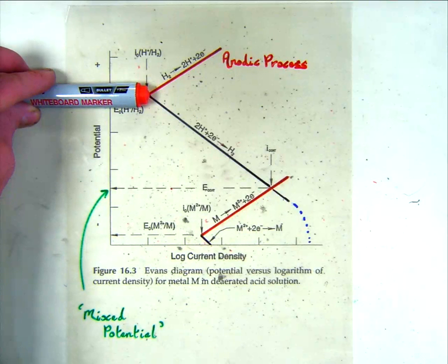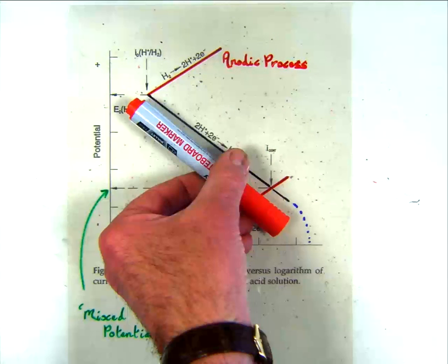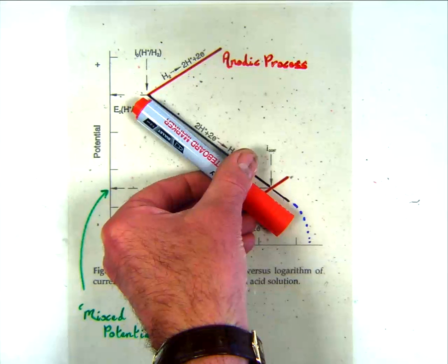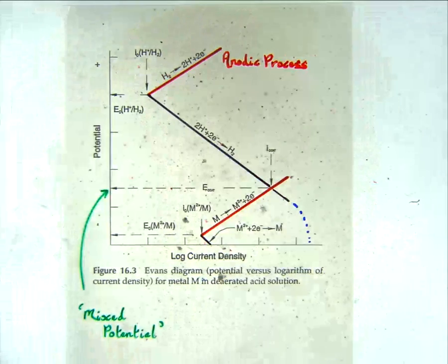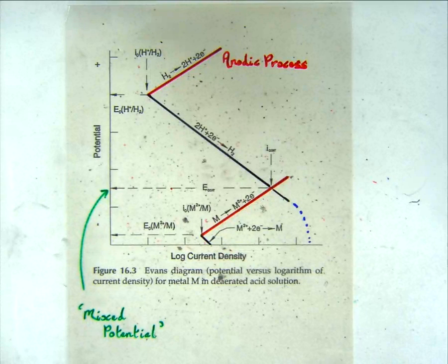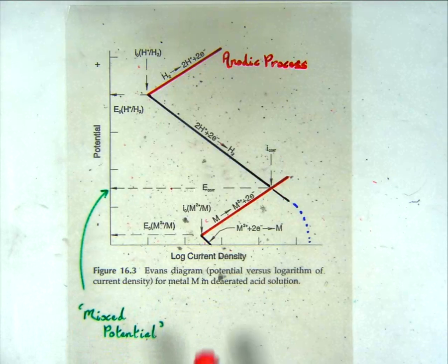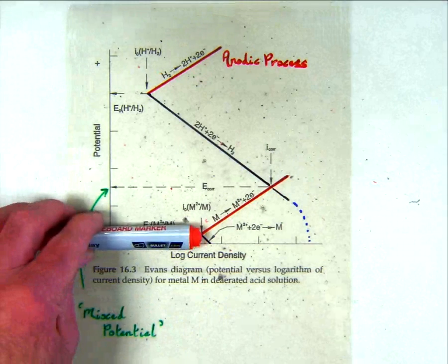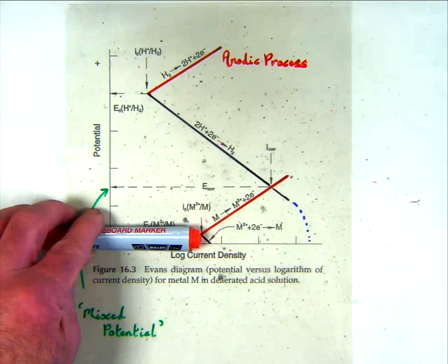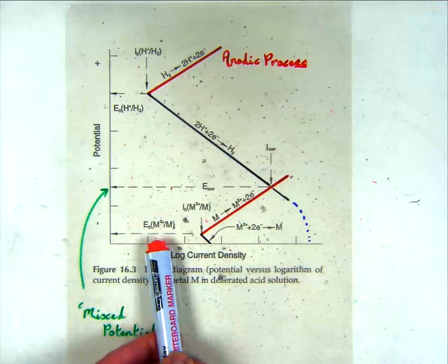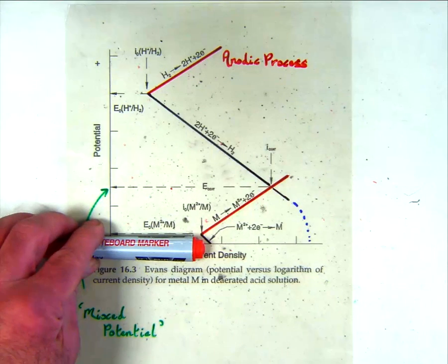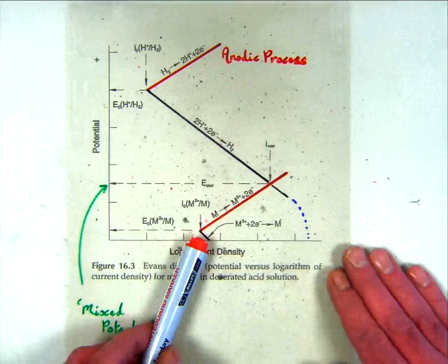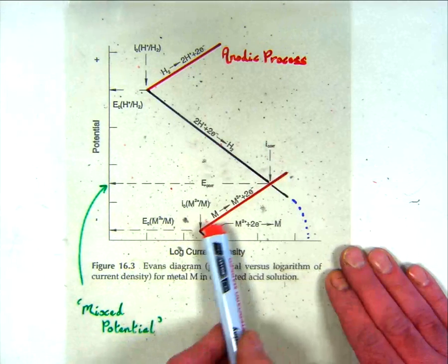There is also down the bottom here another what they call half cell. And this half cell is for a metal oxidation. So that's the equilibrium value. And then there's a possibility of the metal being oxidized, which is the red line here, or reduced, which is the black line that's going off the bottom of the chart, but would actually run off down that way. So again, you've got an equilibrium value plus the option of oxidation or reduction from that equilibrium point.